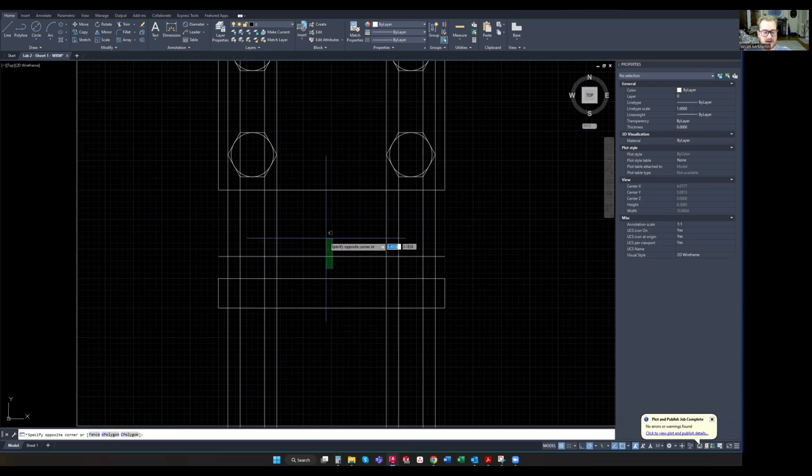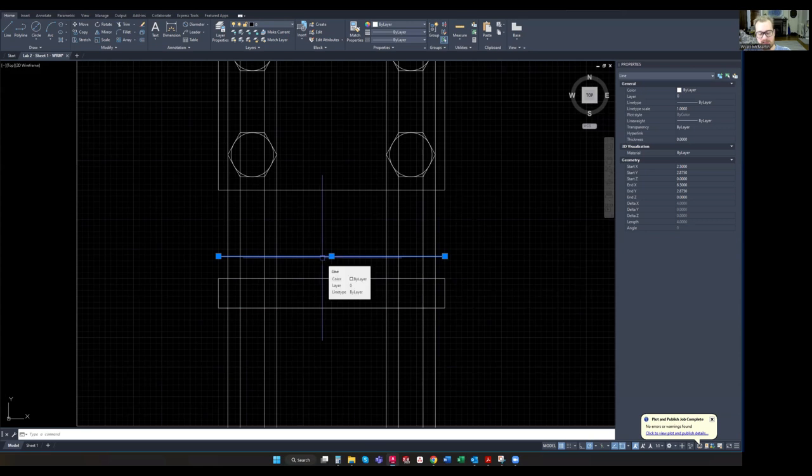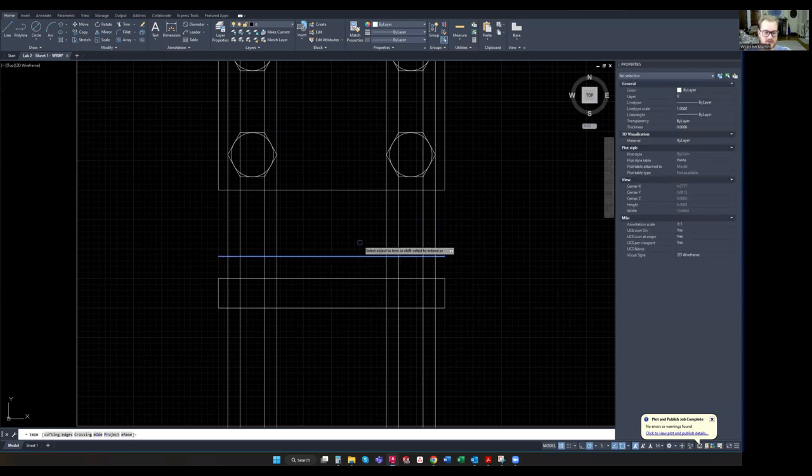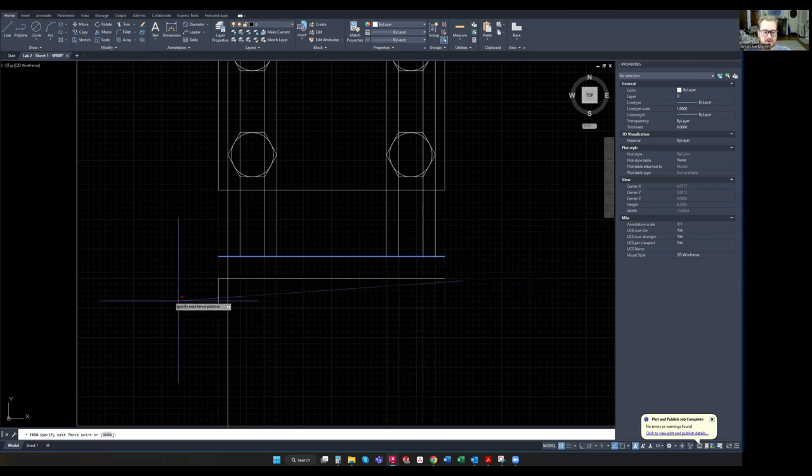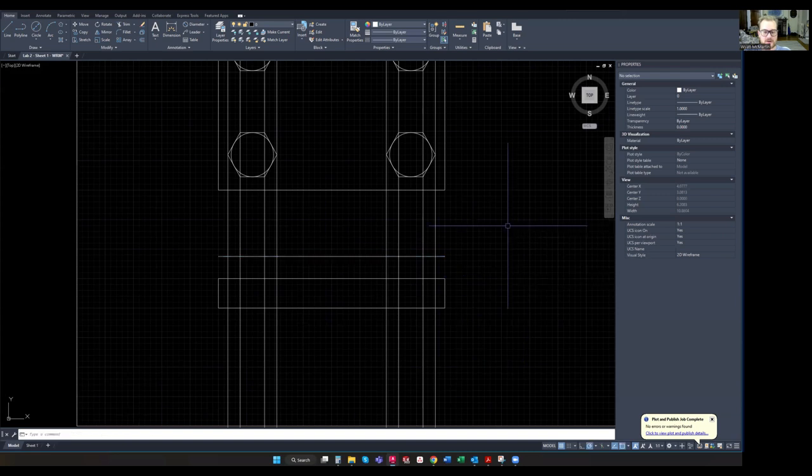So I'm going to highlight this line right here, and then type TR enter, just one time though, because remember last week we did TR enter enter, and that allows you to trim off all kinds of stuff. This week, we're just highlighting the line, TR enter once.